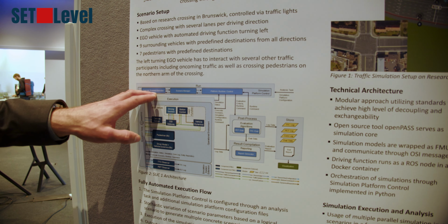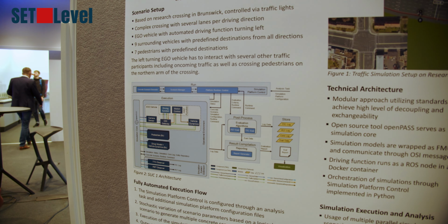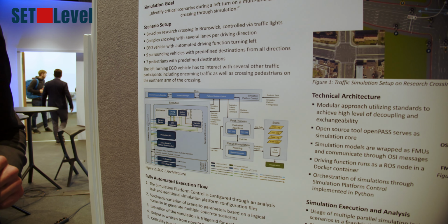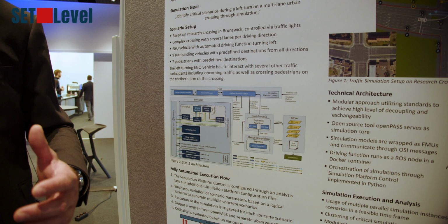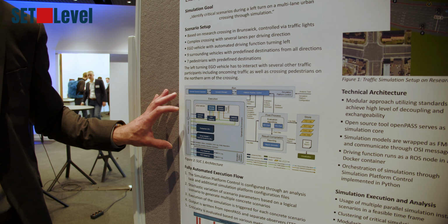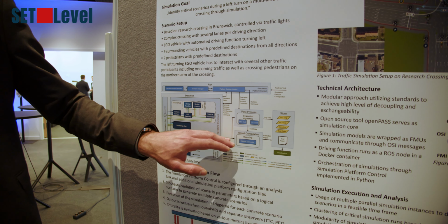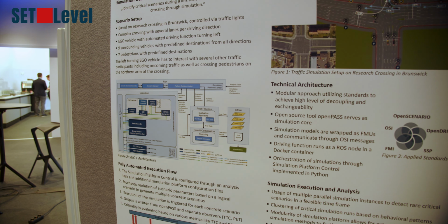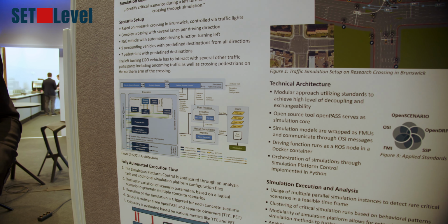And to execute this analysis task, we especially have to apply stochastic variation to the scenario. This is done here by the concrete scenario generator and the scenario manager, which are responsible for applying parameter variation and coming up with hundreds and thousands of different scenarios based on a first logical scenario, as we have seen before. And we can run the simulation for each one of those cases. Afterwards, we apply some post-processing, some result compilation, in order to obtain insights in statistical evaluations over all the different simulations that we did.